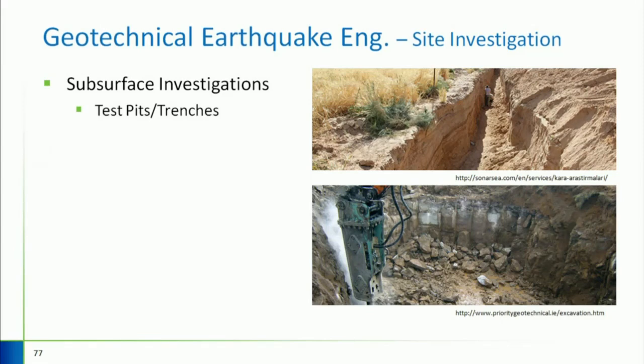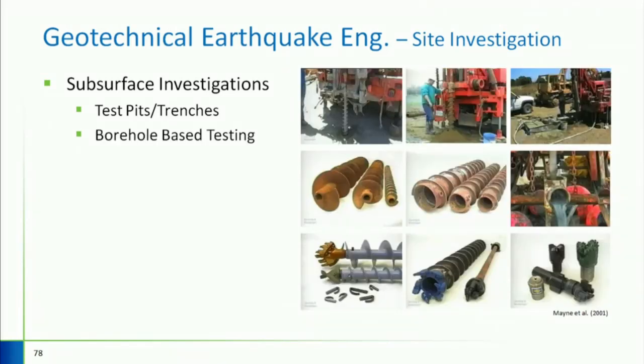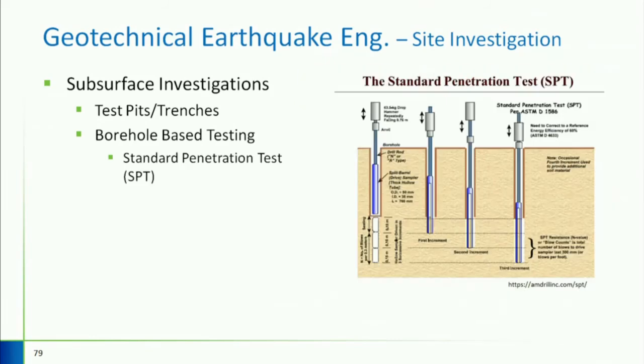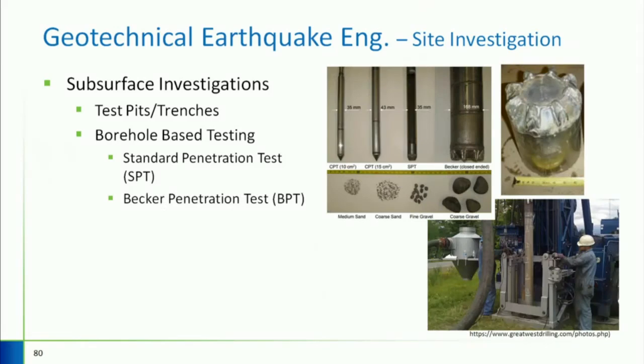Once you start looking at actually invasively checking this, there's test pits. There's boreholes. You can do standard penetration, which is probably the most used. I think they've talked about this in previous training sessions, so I'm not going to get into what an SPT is. Becker penetration, if you're in gravel, it will prevent the SPT from working, so you use a Becker.